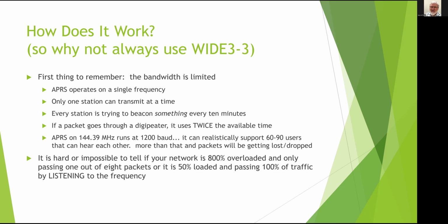On 2 meters, this thing runs at 1200 baud, right? So it can realistically support about 60 to 90 users that can hear each other directly. More than that, and packets will be getting dropped or lost. And if you just turn your radio on and you're listening, it's really hard to tell how busy it actually is. You can't really tell from listening to the audio what's actually going on.